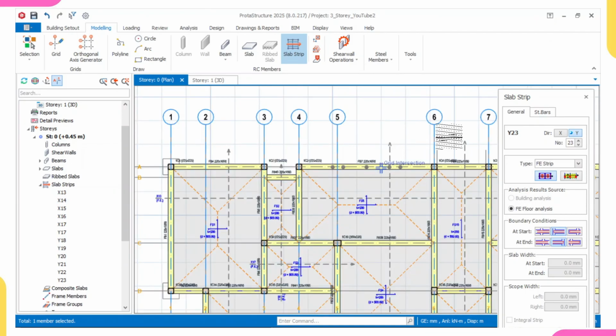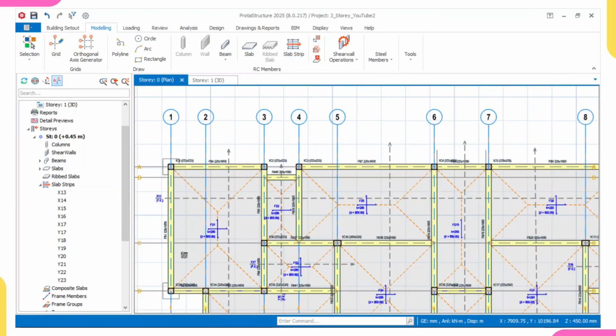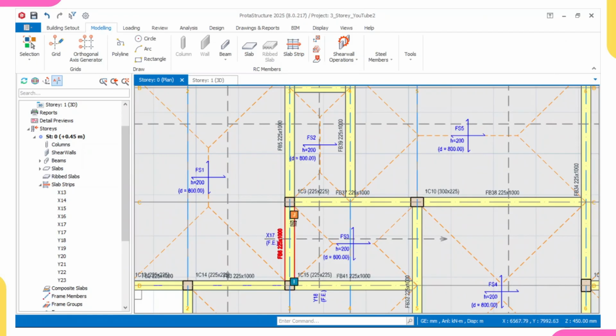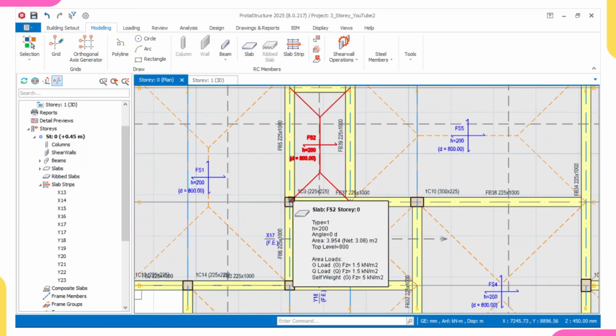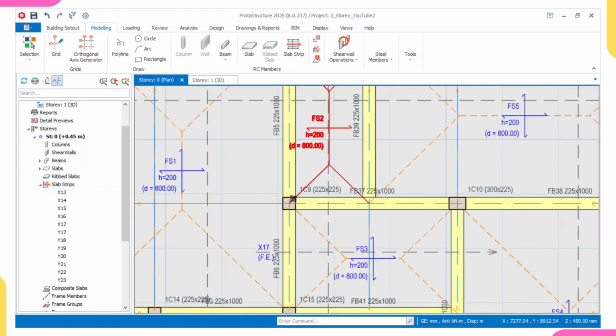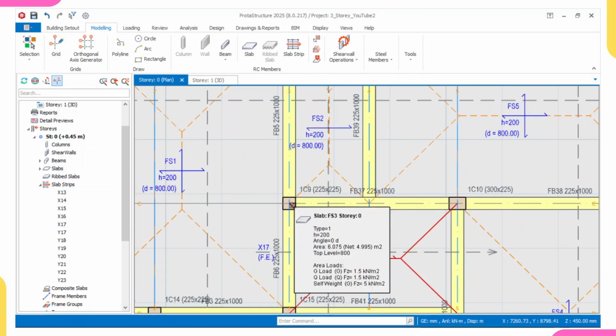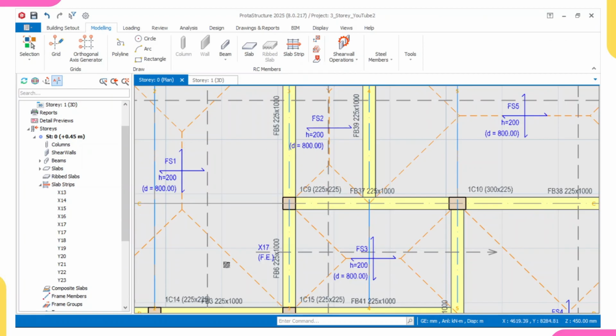Okay, there's something I want to explain here. Let me explain using this column. Once you come over to this column now, let me say this column is carrying a very high load. So at this point, this column will spread its load around this slab. That means this slab will help to distribute the load coming from this column to the soil evenly. Do you understand? This column will spread its load around this slab, and this slab will help to distribute its load evenly to the soil.